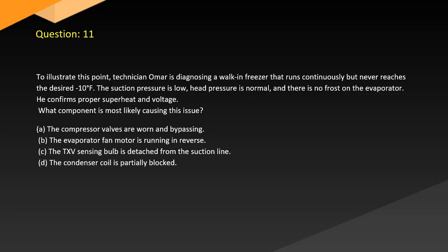Question 11. To illustrate this point, technician Omar is diagnosing a walk-in freezer that runs continuously but never reaches the desired negative 10 degrees. The suction pressure is low, head pressure is normal, and there is no frost on the evaporator. He confirms proper superheat and voltage. What component is most likely causing this issue? A. The compressor valves are worn and bypassing. B. The evaporator fan motor is running in reverse. C. The TXV sensing bulb is detached from the suction line. D. The condenser coil is partially blocked.